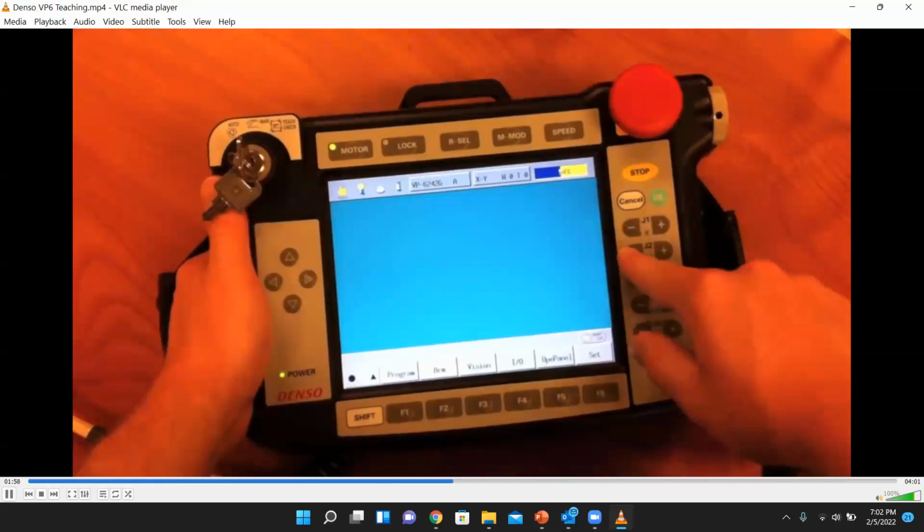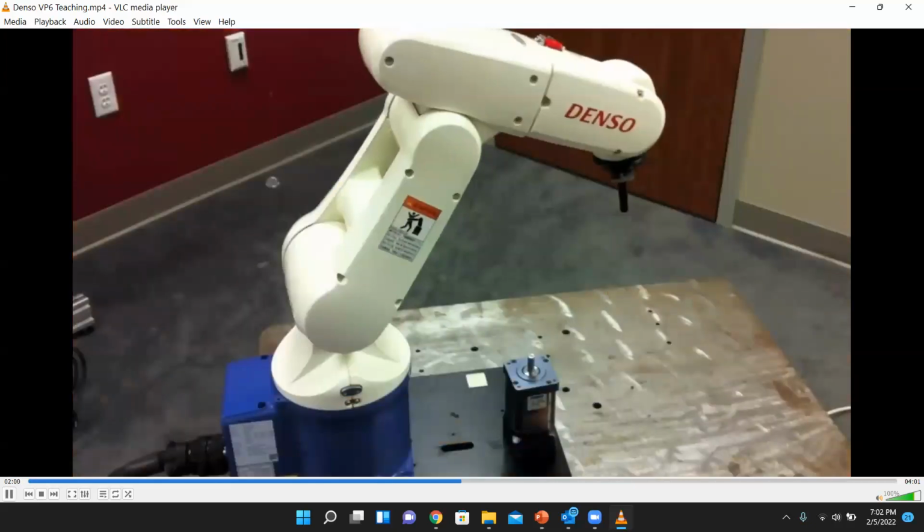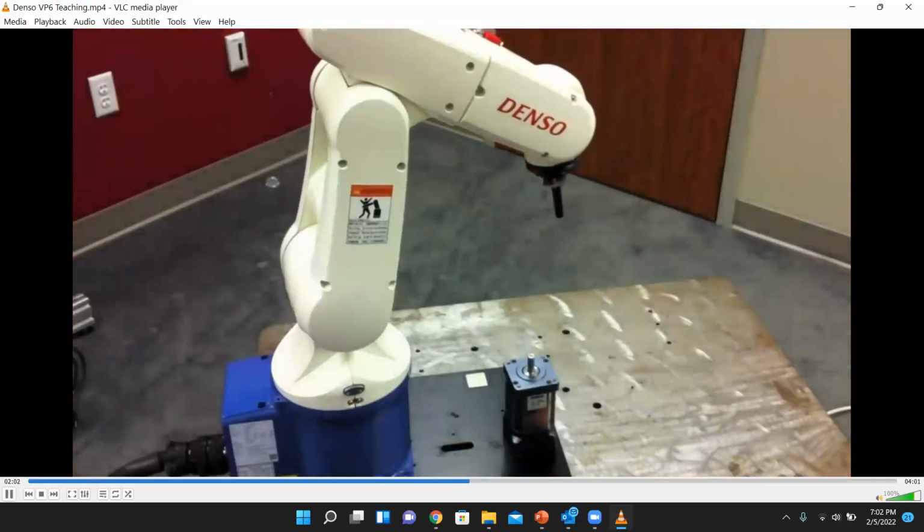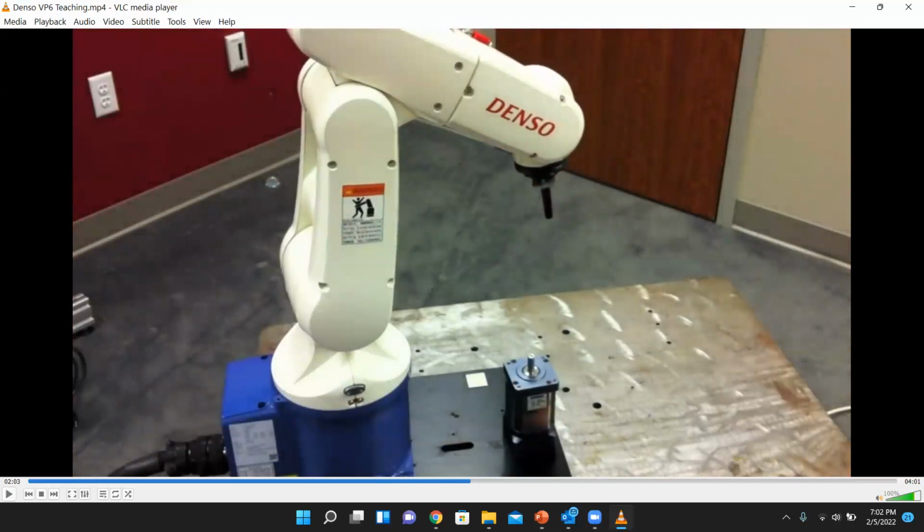Next, what we will need to do is use what we've learned to jog the robot arm into position. Now, you have seen jog motion, which is individual joint motion, and also XY, Cartesian motion. And you know the difference clearly. In jog motion, only one joint at a time moves, and you have no idea where the endpoint is moving.